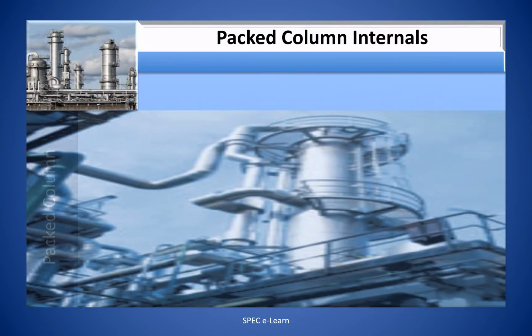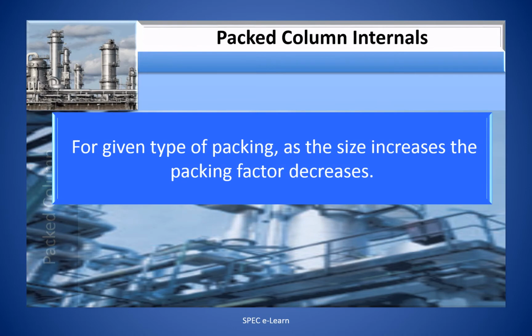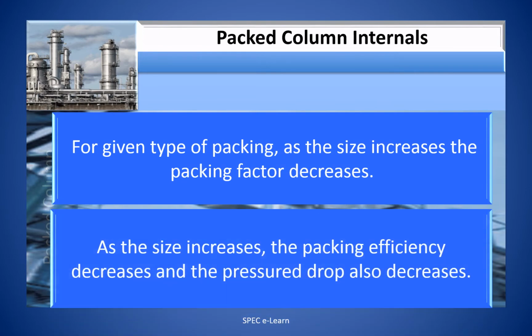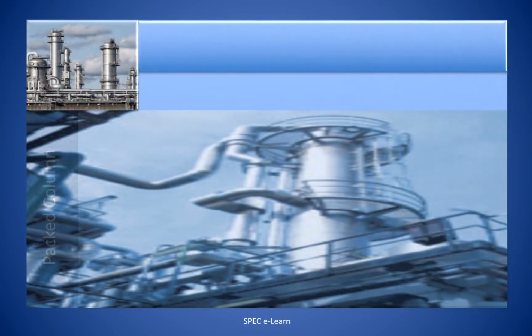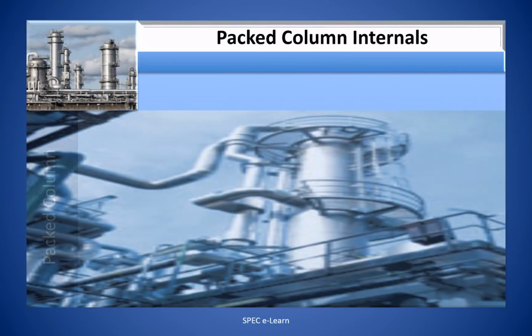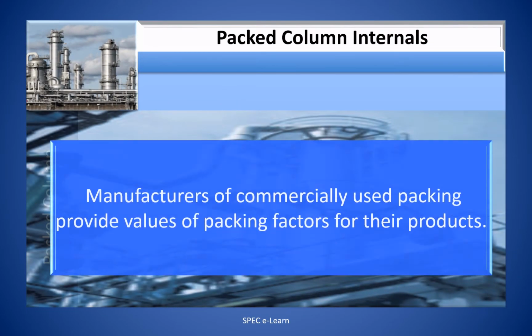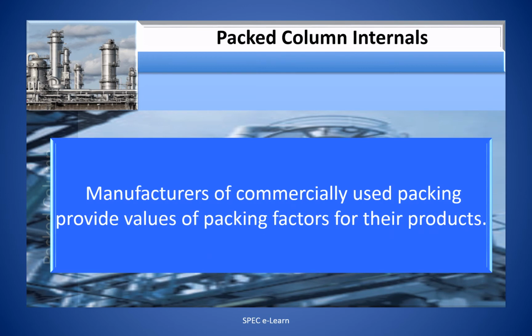For a given type of packing, as the size increases, the packing factor decreases. As the size increases, the packing efficiency decreases and the pressure drop decreases. Manufacturers of commercially used packing provide values of packing factors for their products.